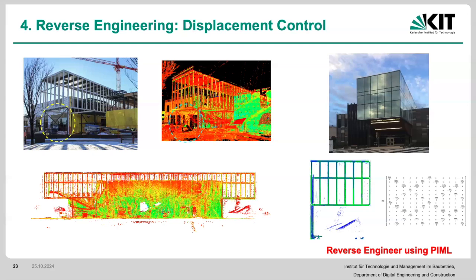But in many other cases, when you have dynamic loading, you need good and fast predictions of these. So you can always use these high-fidelity models, finite element models, to train these neural networks to give you some good, fast predictions.